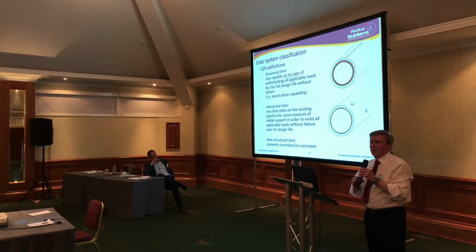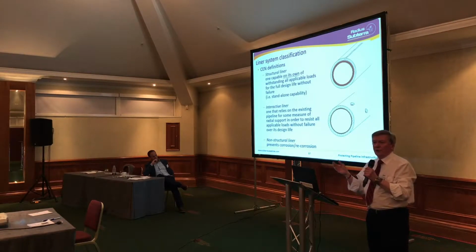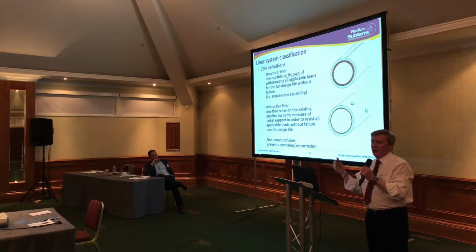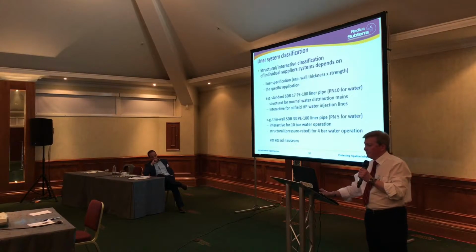And then finally, non-structural liners are those typically spray-applied resins which are used principally to prevent the re-corrosion of cleaned cast iron or steel pipes.